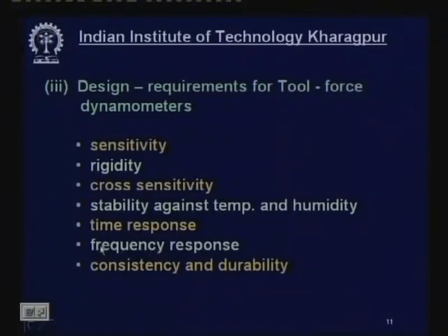Frequency response, that means the dynamometer should be so designed and constructed that the measured values should not be affected or spoiled by the vibration, if there be any, in the machine. Of course, within a range of frequency and amplitude. If the vibration becomes too large, then there is no question, nothing will work, the dynamometer will fail. But within a reasonably large range of frequency or vibration of the machine tool, if any, the measurement values should not be affected. This is called frequency response.